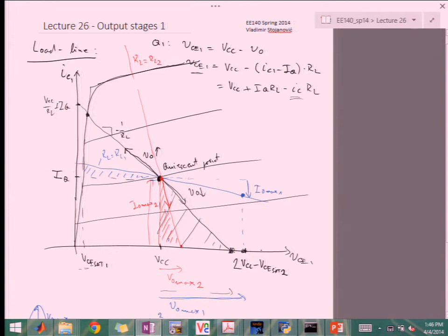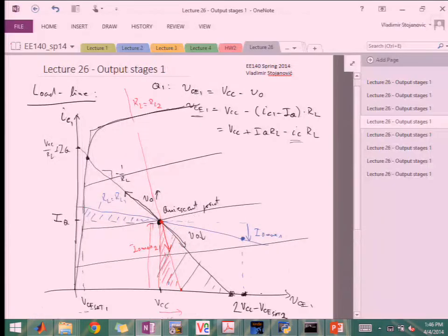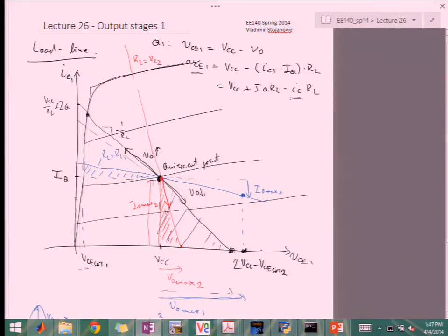So I can keep lowering my resistance up until the point I hit this line. So my load curve rotates. So my load curve can rotate till the point that I hit this exact point. Okay. Notice, because I'm pivoting around IQ, in that case, my IO max is not changing. Right. Yep. We can't really see what lines you're pointing to when you say this line or this line. Do you see this? There is a small dot. Okay, so I'll draw arrows then.